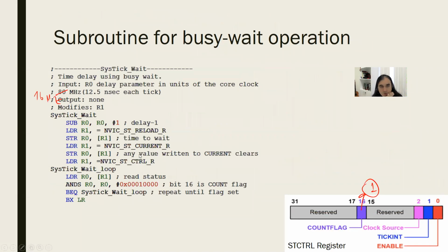How am I going to do it? So there's a subroutine for it. It creates a delay. How much delay does it create? It creates a delay with the value of R0. So in R0, if we have a value, it's going to create a delay as big as the value in R0. So let's say in R0 there is the value 10. Okay? Let's make a test.